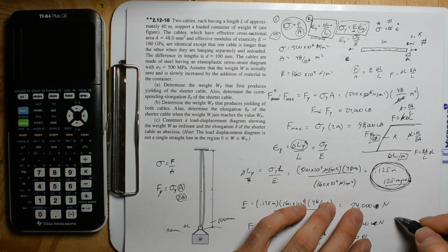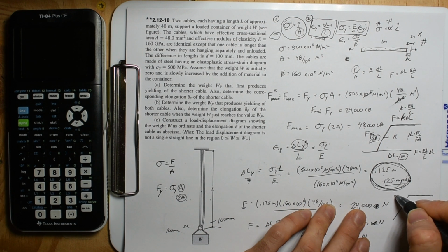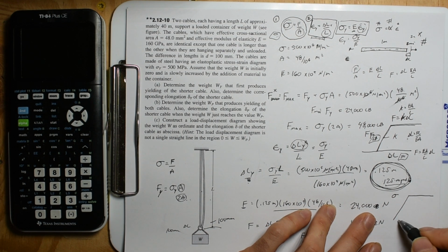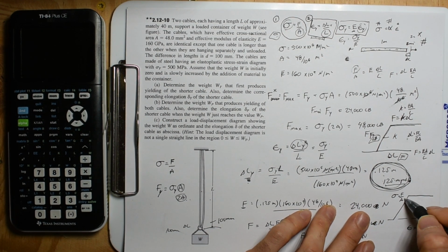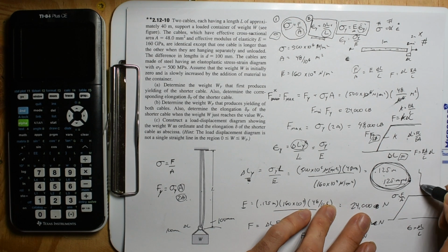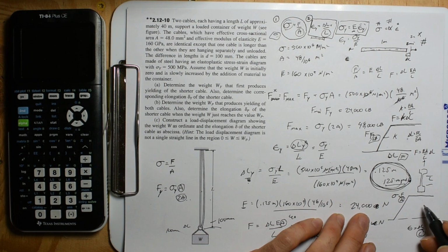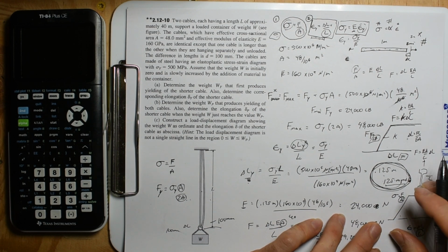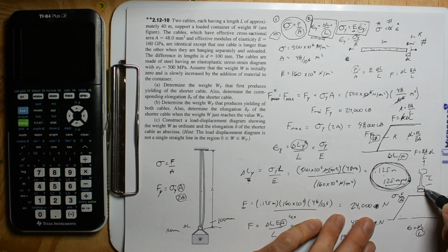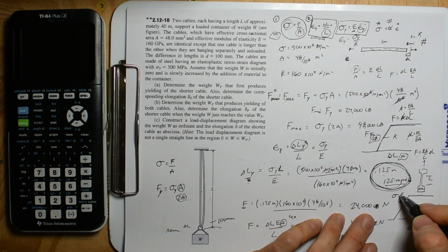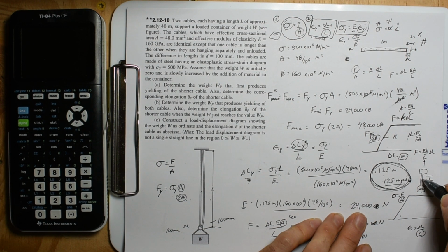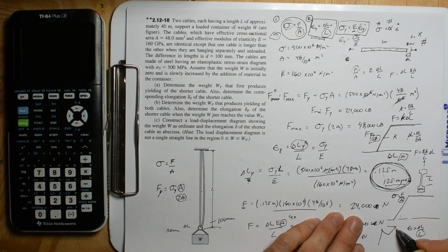And so this graph makes way more intuitive sense than stress, strain. But like I said, this is force over area, and this is change in length over length. You still have to throw a specimen into the machine and tug on it. When you do, you set the area, you set the length, and what you're trying to find is a universal principle of steel that isn't a function of size. So if I put in a specimen that looks like that, and then I go out and build something that's real big, it's going to have the same properties.